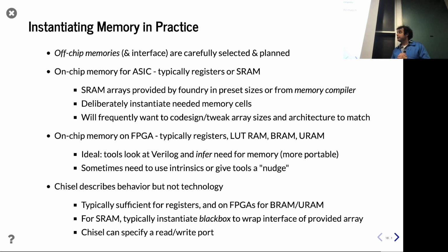And so make sure you perhaps use muxes, whatever you need to do to make sure that if you have a lot of people who want to access that memory, they arbitrate first, and the actual requests come in only through 2 ports of that memory. And that's one way to kind of guarantee you get BRAMs on FPGA. Cool, question.